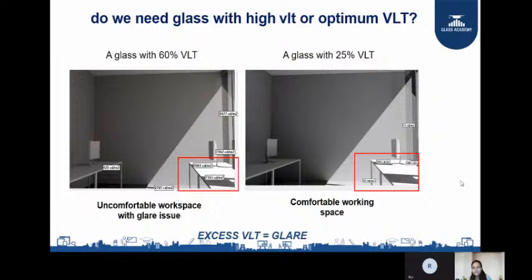So by global standards of fire resistant material, how do they classify fire resistant material? The first is E, which is integrity, then we have EW, and then we have EI. So first we will talk about what E is. E is the integrity. It prevents the spread of flame from the fire site to the non-fire site, and it will not collapse during the fire. You can see here, if there is a fire, it will allow the radiation, but it will prevent the spread of the flame.